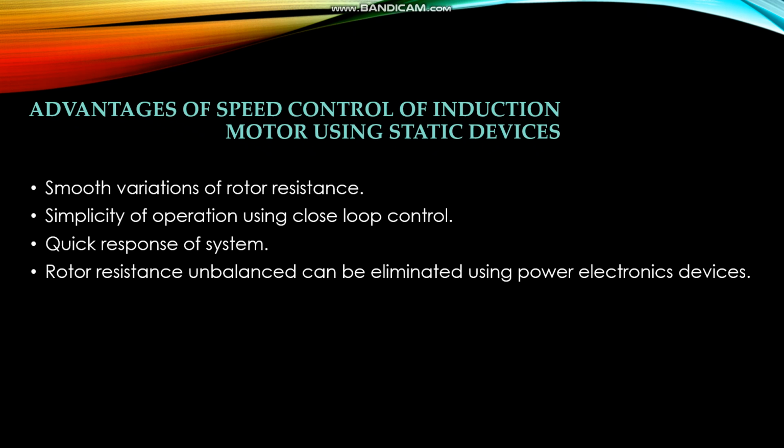Next, advantages of the speed control of induction motor using static devices. Smooth variation of the rotor resistance. Simplicity of operation using closed loop control. Using this, the response of the system is very quick. Rotor resistance unbalance can be eliminated using power electronic devices.